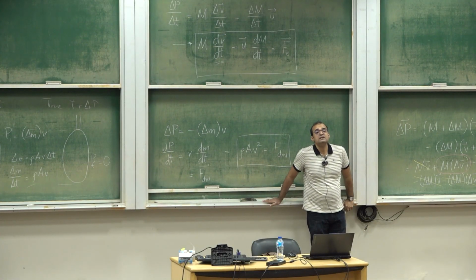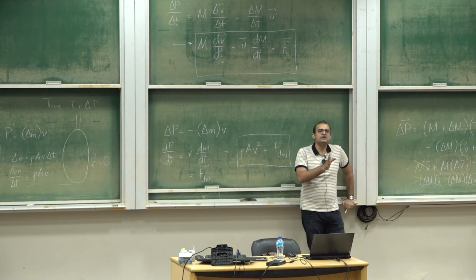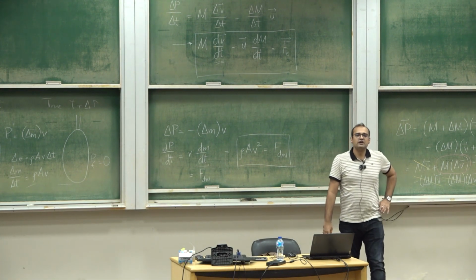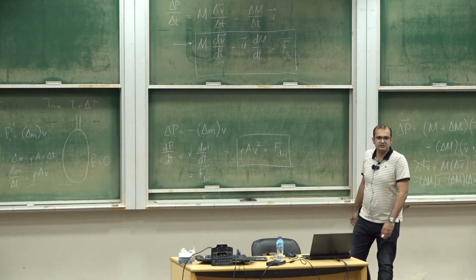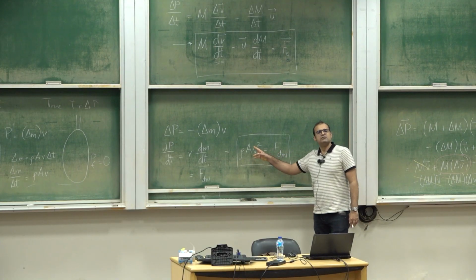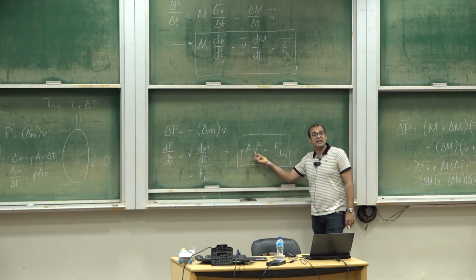क्या लगेगा? हाँ, of course, in general that depends on कि air molecule को collision के बाद क्या होता है exactly, और किस एंगल पे आके wind लगती है. So assuming कि वो बिल्कुल normal लग रही है और रुक जाते हैं, then that's what I find. Okay. Notice ये एक्सप्रेशन हमको क्या बता रहा है? That the force exerted is proportional to the square of the wind speed.